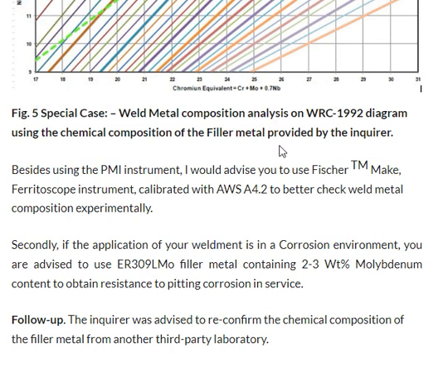When joining two dissimilar metals, direct the arc energy towards the stainless steel side rather than the carbon steel side, so we can prevent the dilution of carbon into the weld metal composition and minimize any risk of reduction in the ferrite number and ferrite content. So we can avoid the risk of solidification cracking.